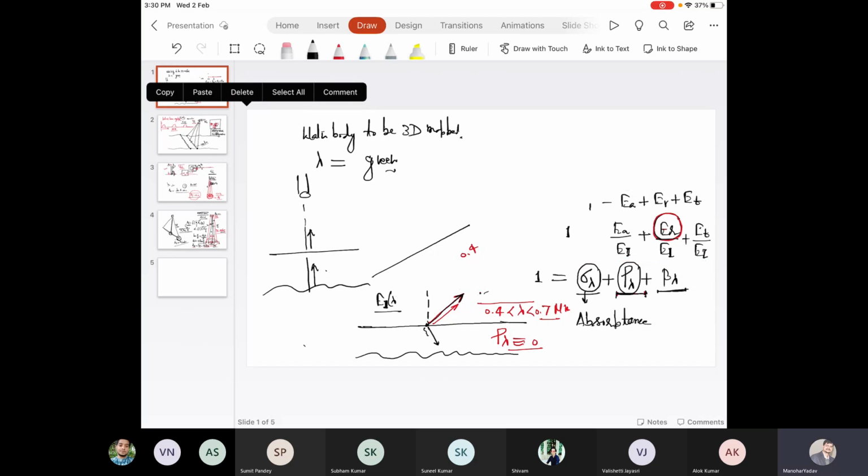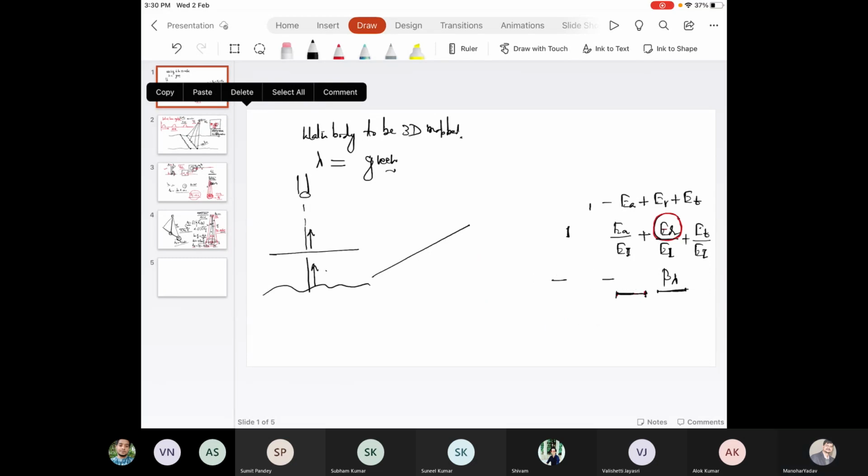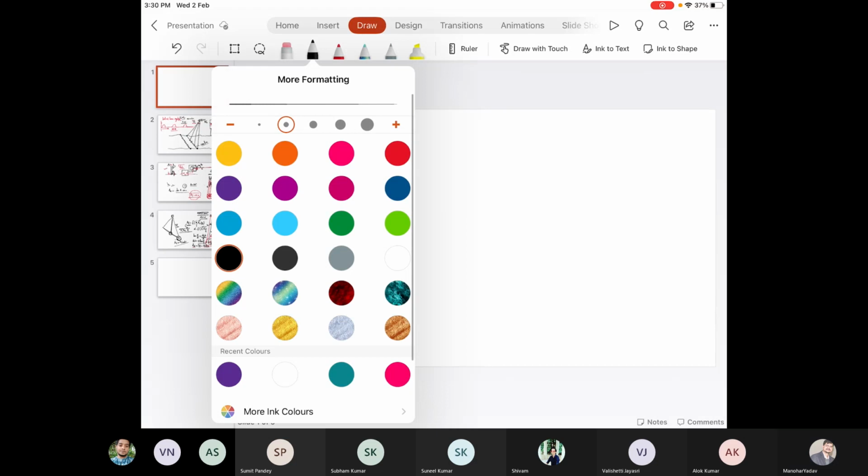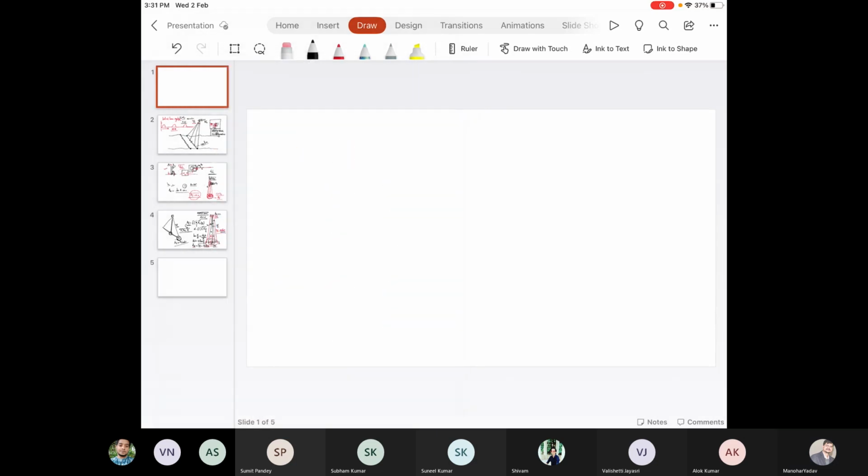Now we'll see the property of laser beam, and we'll analyze that property in terms of data quality. Okay. So there are certain limitations of internal electronics of LiDAR instrument that we'll see on the basis of parameters. So the laser source which generates the laser beam